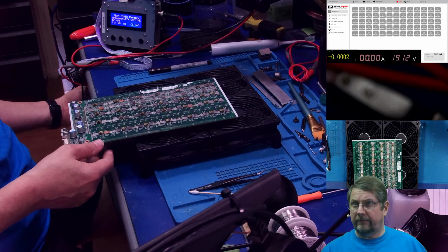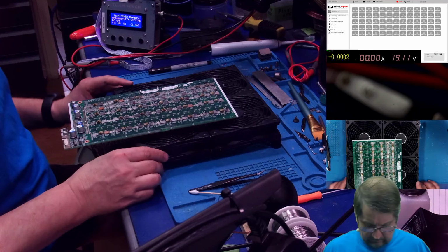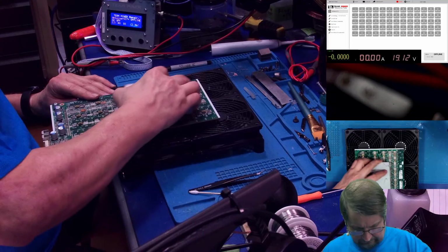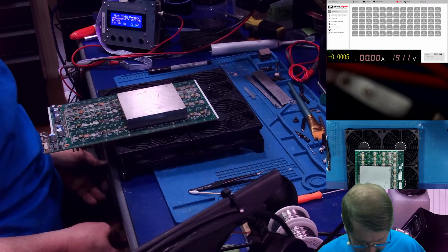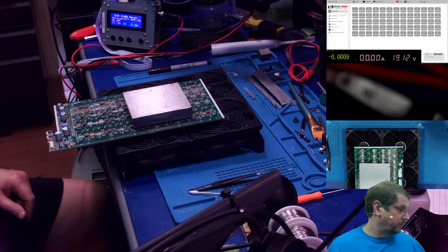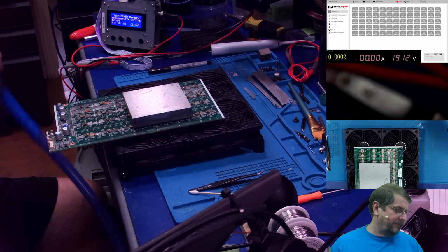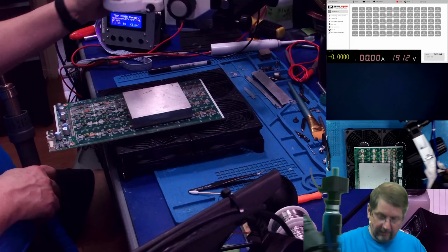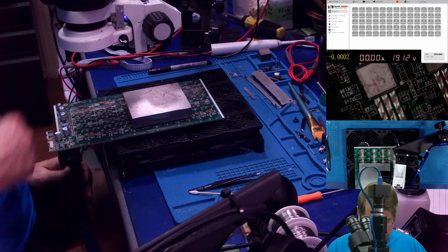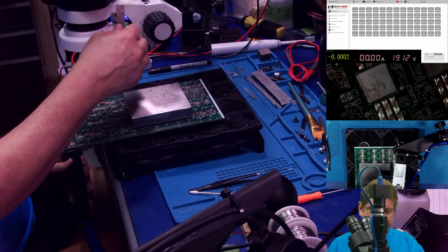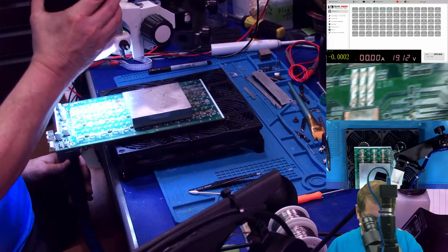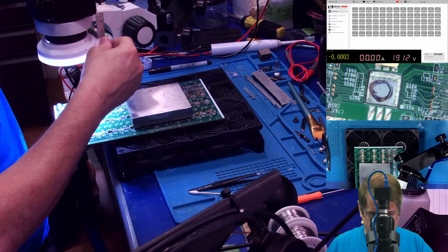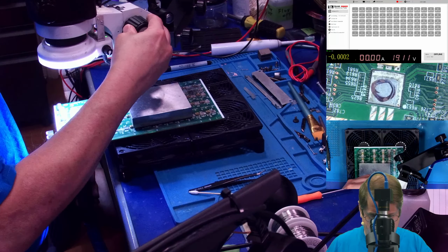Turn the air off. Get my hot air ready to go. Cool. All right, 425 is the temperature and 80 on the airspeed. The max on this unit is 120, so it's not 80%. Just FYI, I'm trying to save you the headache of something I learned.